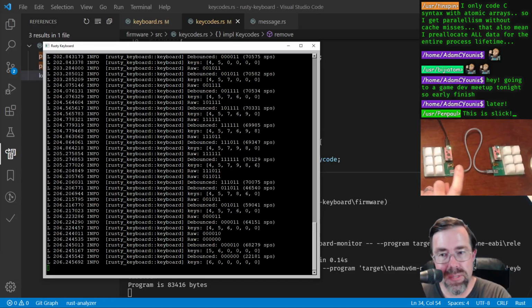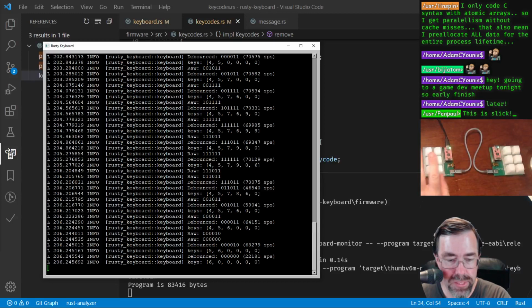And the next step is to form a key code report that we send to the computer, and we have exactly 6 slots, so we only can register 6 keys down at once over USB. And that's at the point that I'm rewriting that code today, and I'm making sure it works.